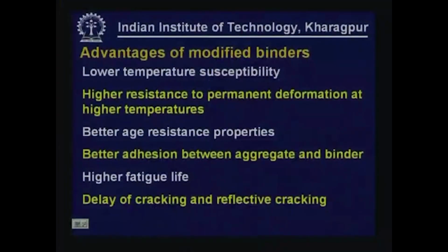Similarly, these binders are generally known to have better adhesion to aggregates. The mixes usually have higher fatigue life, and there is also delay in the initiation of cracks, and lesser reflective cracking problem as well.